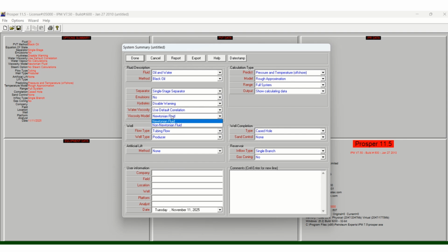In Newtonian fluid, you use it when viscosity remains constant. That is for fluids that have a constant viscosity, irrespective of the shear force that is applied, whether the fluid is turned around, or whatever the fluid goes through, the viscosity still remains constant. Then in that case, the viscosity model that you should choose is the Newtonian fluid.